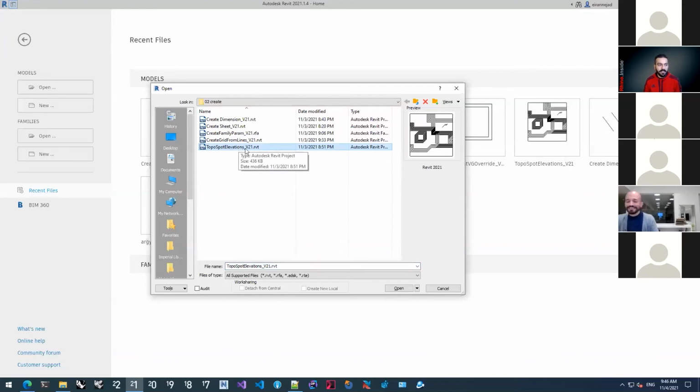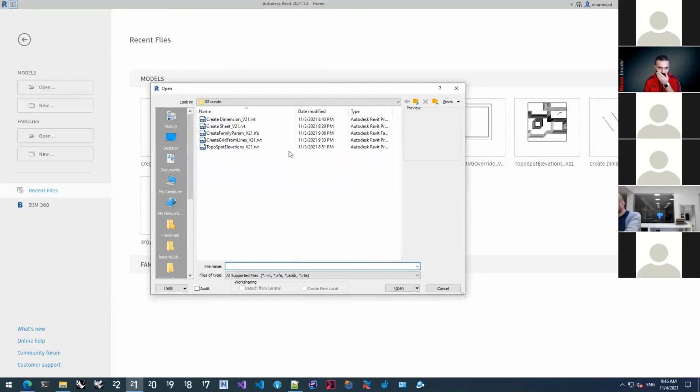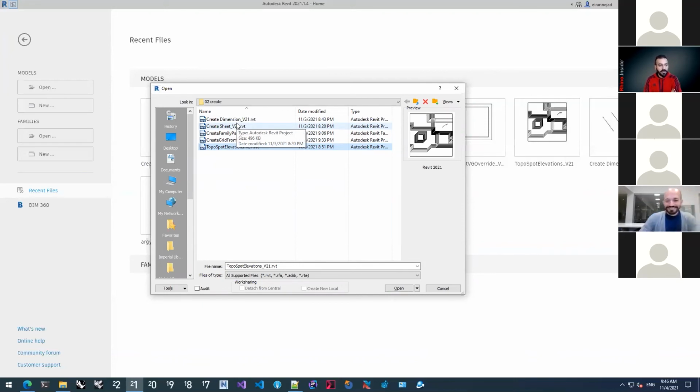That's all there is. And just to clarify, it's true we can find out information from a linked document, but you can't make a transaction into a linked document, correct? And actually change it. Linked documents you can query all you want, but as long as they're linked inside another document, you can't make changes to them. You have to, through the Revit API, open it in the UI, make some changes to it, close it, and reload it back again. It's kind of the way the UI works. Yep. So it's slightly more complicated that way.